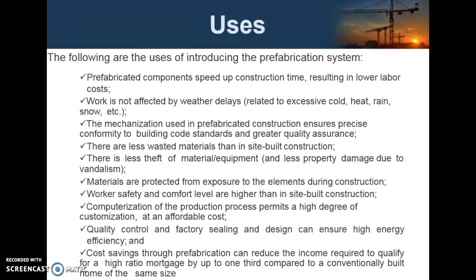These are the main uses of introducing the prefabrication system. The first one is time saving, and the second one is the work is not affected by any weathering condition, and the greater quality is maintained throughout the construction, and also the higher conformity to building code standards. There is less wastage of materials at the site, and also less theft of materials.